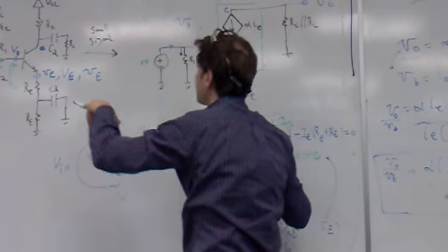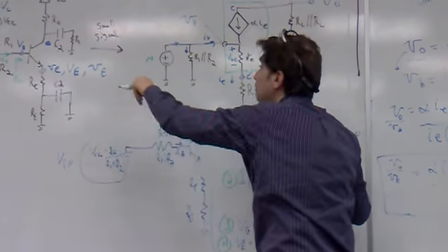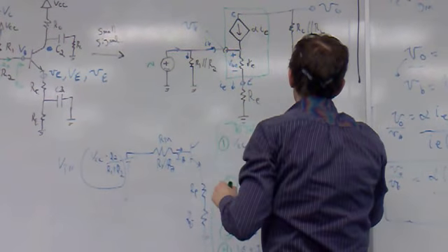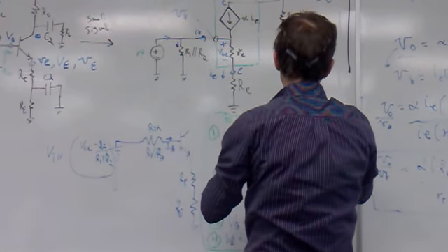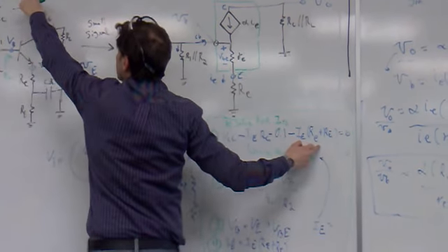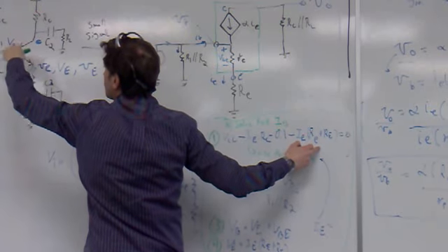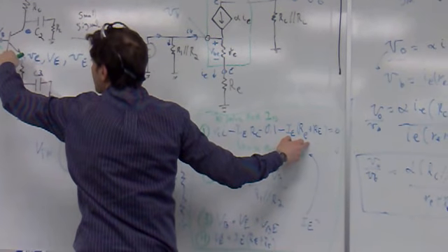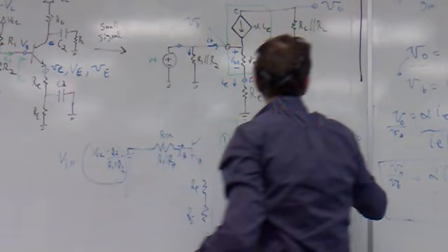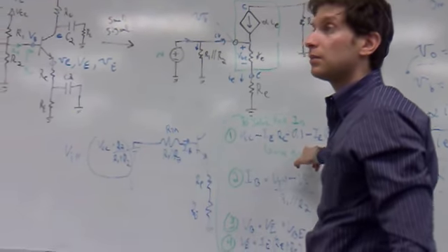So I'm saying IE times RC minus 0.1, which is this thing. You can actually even ignore this. Minus IE, which is, again, in this equation, which we can factor out, times this, right? So VCC minus this, minus 0.1 for this guy, minus IE times this guy, minus IE times this guy equals 0. Can I solve for IE in this equation?